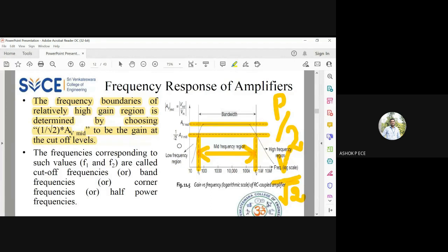That is fine. My device should always have a minimum of 50% power, because when you design an amplifier, it should have a minimum power available and a maximum power available. It should work always between minimum and maximum power. Here I fix the minimum power to be 50% and the maximum power to be 100%. The frequencies where you get the minimum power are F1 and F2. So you should always operate the device only between the frequencies F1 and F2.